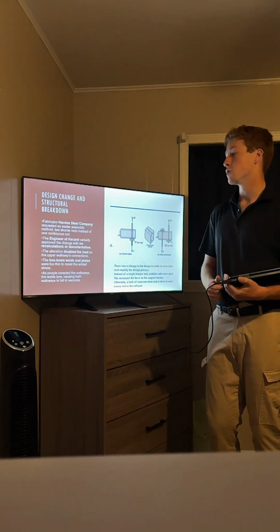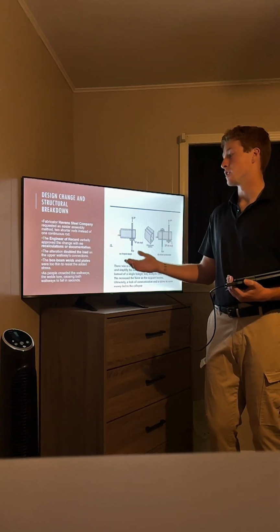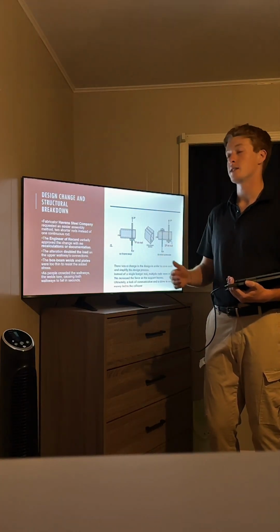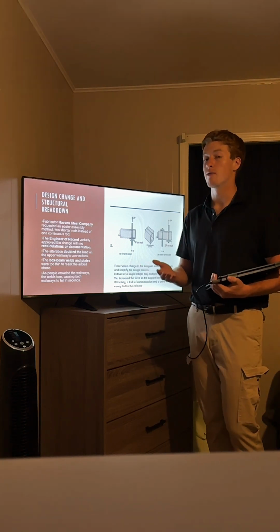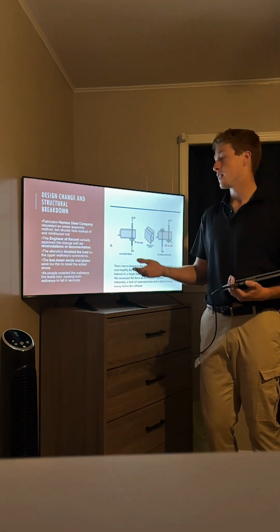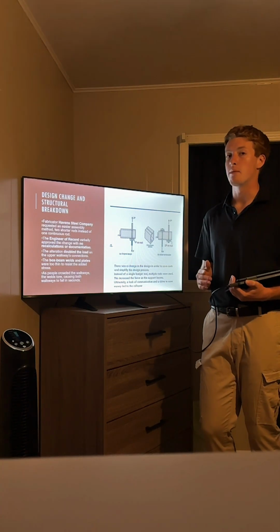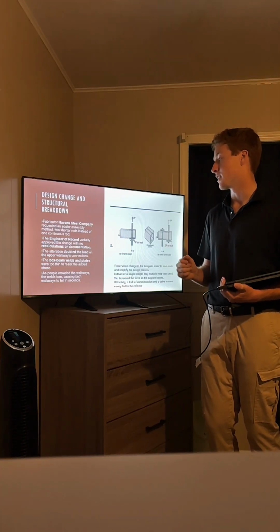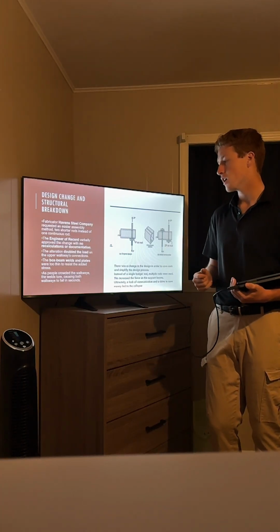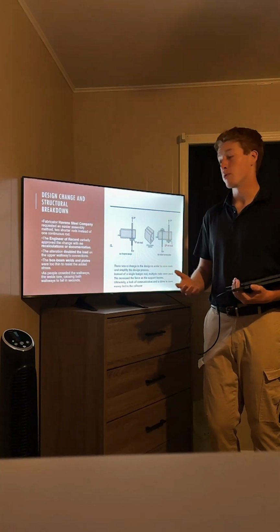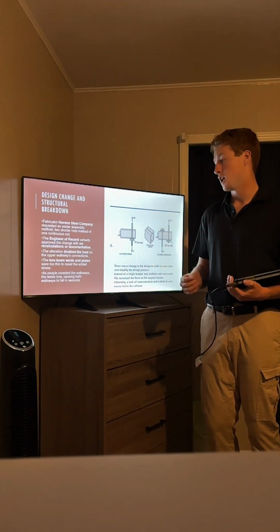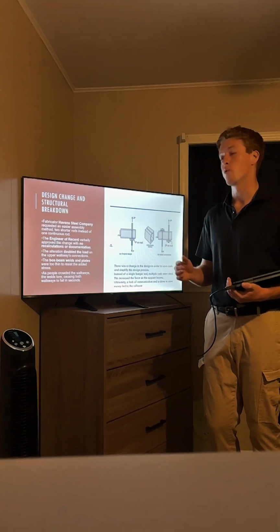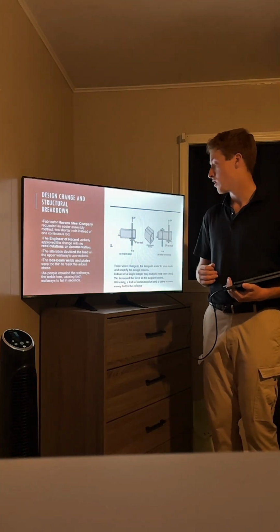The box beam welds and plates that were used were too thin for this project to resist the added stress. What was initially supposed to be used was going to be able to hold it, but when they doubled the load, these welds and plates were no longer able to withstand the pressure. And eventually, when people crowded the walkways and walked all over it and added weight and stress, the welds tore, causing both walkways to fall in seconds.